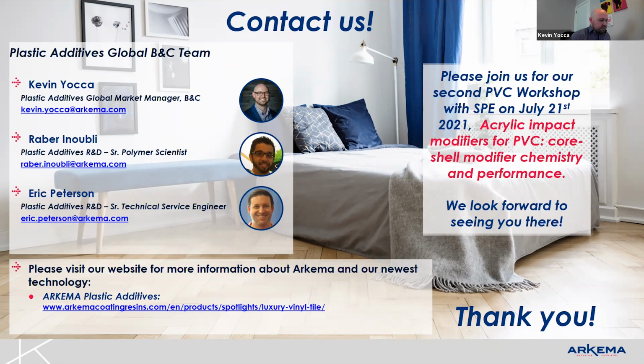Yeah, so the main one I talked about was the DSC. That ASTM standard for DSC, finding basically the processing temperature and percent crystallinity, is probably the most fundamental way to do it. Now, if you have an application where, say, impact strength is important, honestly, another way to do it is try some different settings and do some drop dart and see where you are below where you want to be, where you pass through the optimum, and where you then fall off on the other side, whether there's too much heat and torque. So you can make a nice process window study for yourself.